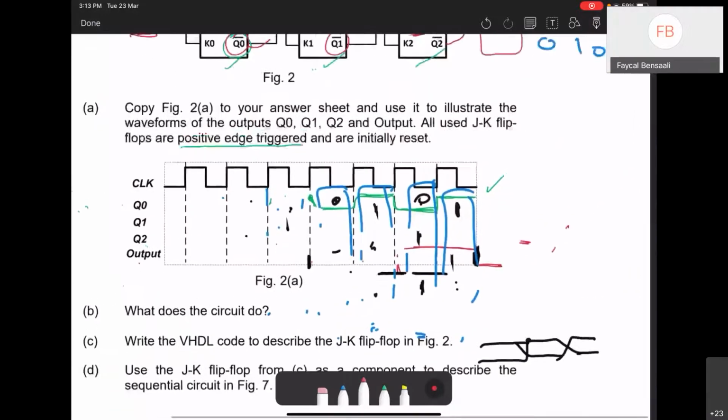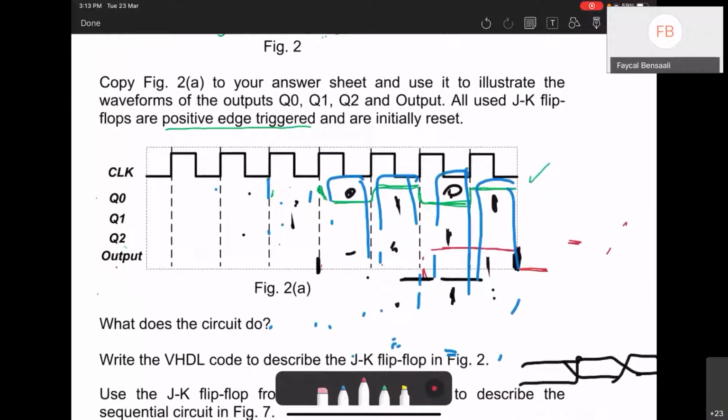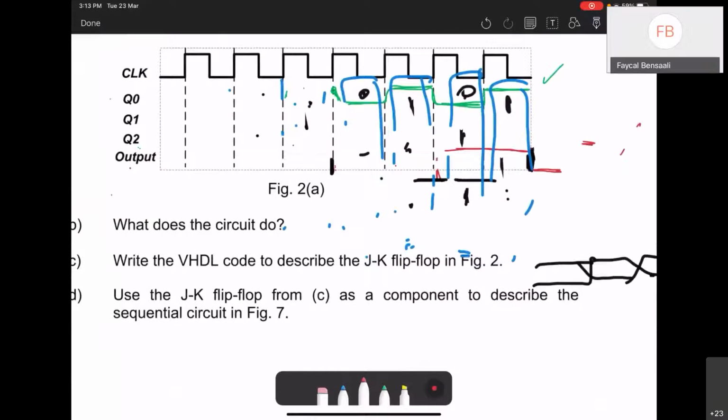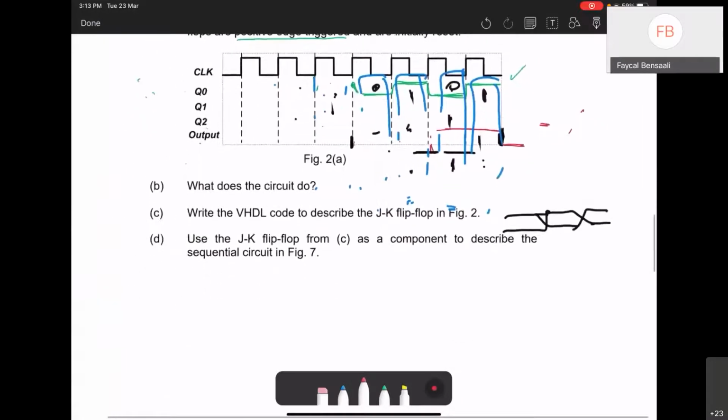For the 3-bit one, it goes to maximum 7 and then 0, 1, and then it repeats again every clock cycle. Once you stop the clock, if there is no clock, it will remain as the last value. So if it stays at 1, it keeps displaying 1. Right.